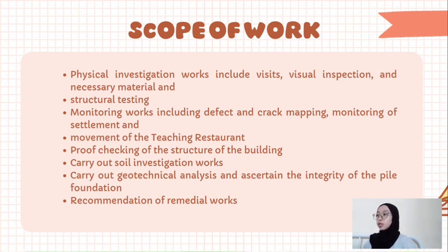The scope of work included physical investigation works, including site visits, visual inspection, and necessary material and structural testing. They also had monitoring work, including defect and crack mapping, and monitoring of settlement and movement of the teaching restaurant. They also did proof checking of the structure of the building and carried out soil investigation works.